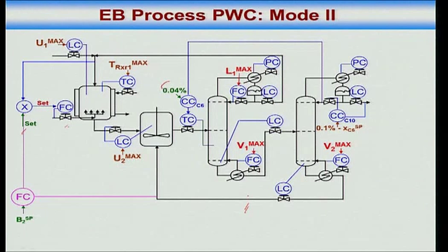Okay, so what I do is this. Now does this make sense? Does this make sense or no? Yeah. So now these are my two unconstrained degrees of freedom. This and this. These two set points the operator can play with. These are the same as I had told you earlier: product benzene impurity, and DEB recirculation rate. Okay. Alright. So I've synthesized the control structure.